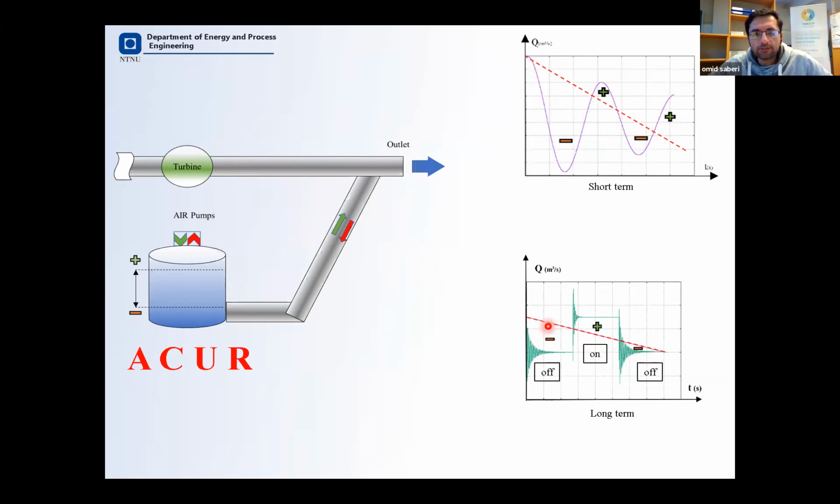Yeah. The key is simple mathematics. You should design these things flexibly. For example, this volume is injected from the reservoir, and this one goes to the reservoir. You should design it so that the sum of the positive volume is equal to the negative. This is the mathematics of how much water you get and how much water you give, and making them equal. This is the key of the calculation.